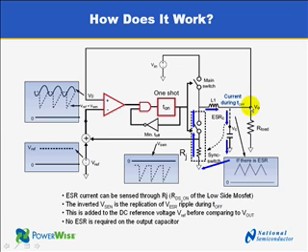So how can we get rid of this ripple? We take the ESR and move it in the closed loop to this position here. There we can still take the voltage across this resistor and use it for regulation. But we avoid any resistor in series here. So we have a small or no resistor in series with the output capacitor. So we have almost no ripple at the output. This is exactly what we need.